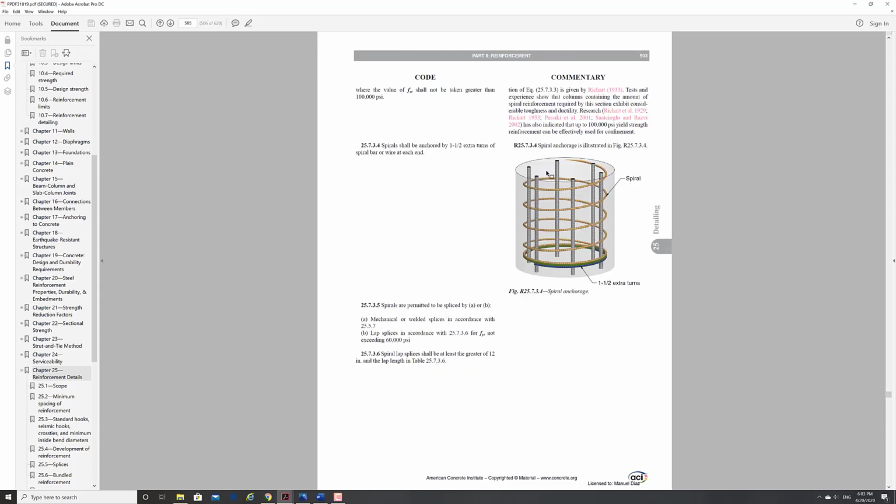All right. So I think those are the nice stirrups. Here is the 1.5 extra that I showed you in the photo, right? You have to turn around to make sure that the ends of the spiral go at least 1.5 turns extra. Okay. So these are very nice drawings. I wonder what software they use for doing this.